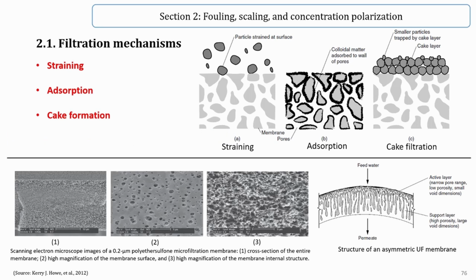The adsorption capacity is quickly exhausted. However, adsorption is not an effective mechanism in long-term operation of membrane filters. However, adsorbed material may reduce the size of pores at the membrane surface and improve the ability of the membrane to retain smaller material by straining.